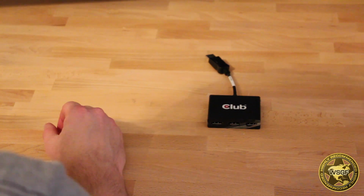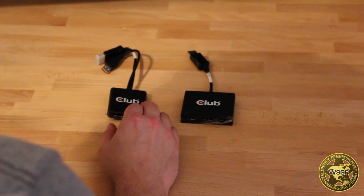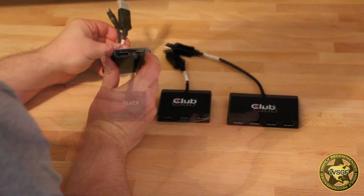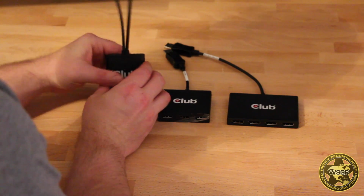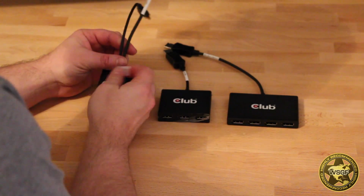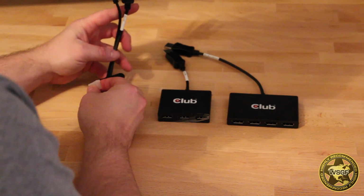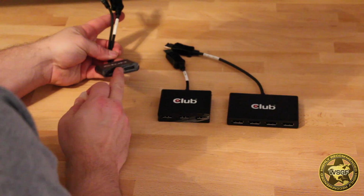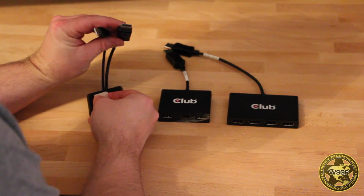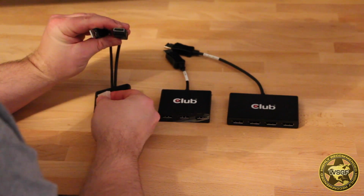But if we take this unit out and we bring in the rest of the lineup, we have here the 2x1, and then we have the 4x1 here. You can see the two outputs, the one input. What you'll notice is that there is no DC input. This one is USB powered. You see the USB port here. It is geared towards notebooks, so you can easily add 2 monitors to one notebook. You'll note that it is full-size DisplayPort. Most notebooks are going towards mini DisplayPort, so you may need an adapter.